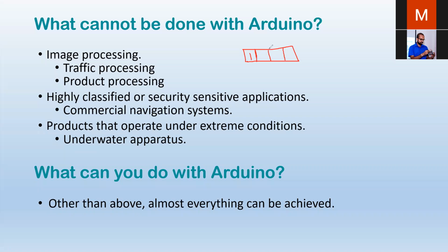There are output registers, input registers, and so on. If you put 1 in an output register, that pin becomes high, and when you put 0, that pin becomes low, right? This is the basic idea. Anyway, digitalWrite and digitalRead handle that for you, so you don't have to do that. If you had to, it's really hard. So that is what the bootloader and this nice programming language do. So yeah, I think you got that.